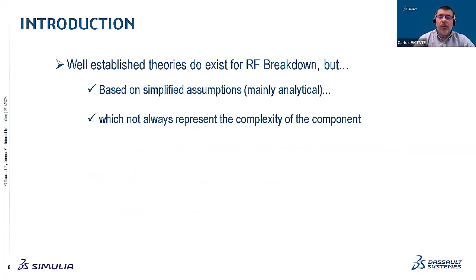The point here is that there are, from all times, I would say, well-established theories for analyzing RF breakdown, both multipactor and corona. However, such theoretical approaches are based on simplified assumptions, such as simple field distributions, because they consider only one dimension, and simplified material properties. They are even limited in signal types, so typically only continuous wave signals can be analyzed.